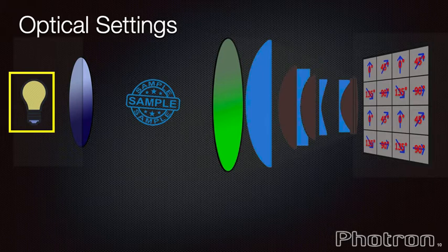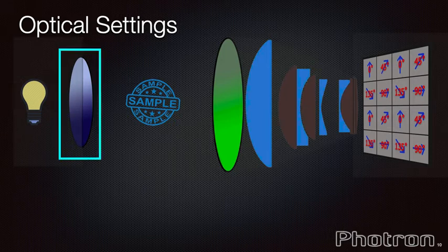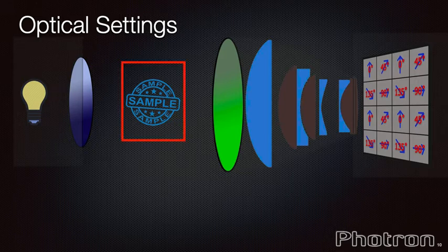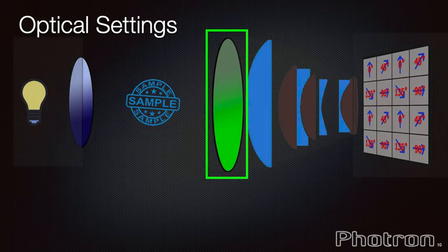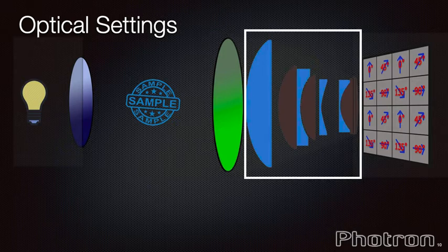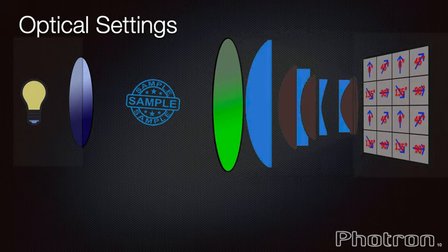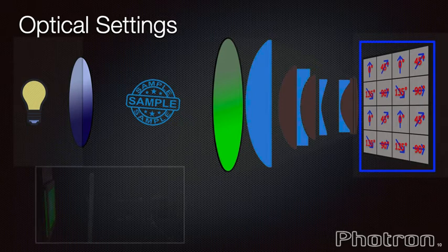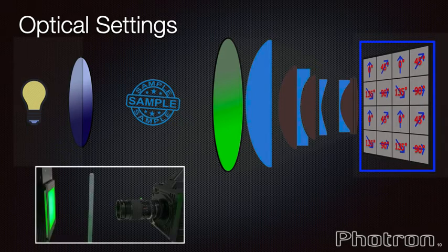Our typical polarization imaging test setup comprises a light source for the Crysta, in this case 520 to 530 nanometers, fitted with a left-hand circular polarizer. The sample being tested must transmit a minimum of 30% light through it. In front of the optics we utilize a bandpass filter appropriate to the wavelength of the light source. And then conventional optics. The Crysta comes with both Nikon F/G bayonet mounts as well as the threaded C mount for mounting to a microscope or similar optics. And lastly, the Crysta has a high-speed CMOS sensor equipped with a photonic crystal polarizer.